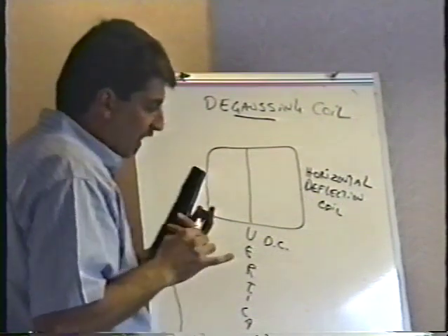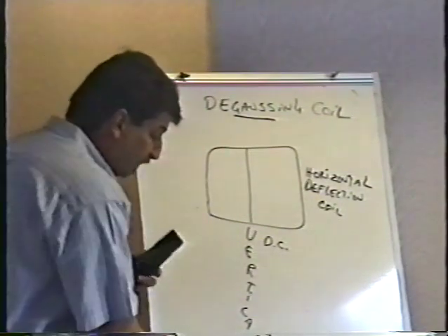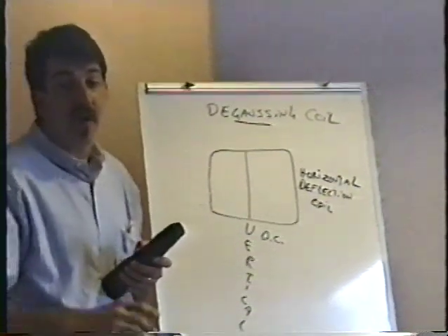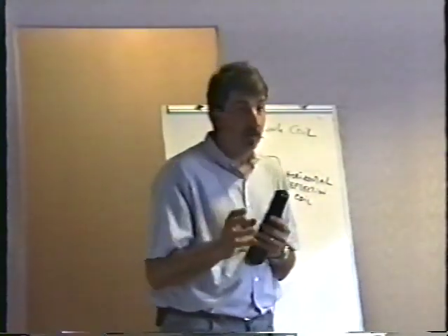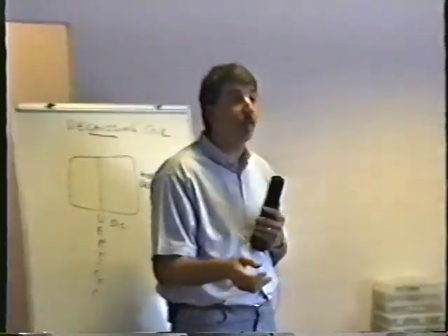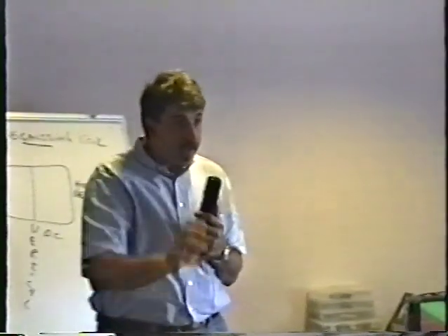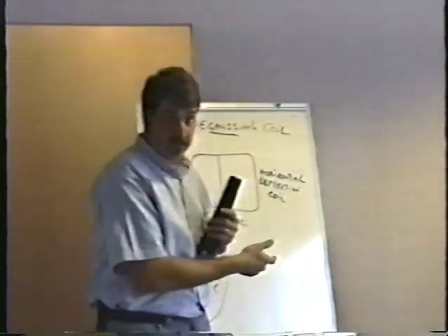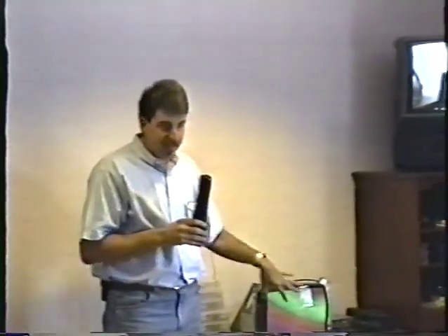The degaussing coil comes on automatically whenever you first turn the monitor on from a cold start. It only works when the monitor has been off for a while. It has to be off for about 20 or 30 minutes for it to operate. It automatically comes on whenever you first turn the monitor on and demagnetizes the picture tube. That's important, not just to keep kids from hitting the games with magnets, but because the magnetic field of the Earth is what magnetizes the picture tube. The same thing that makes the compass needle point north also magnetizes the picture tube.